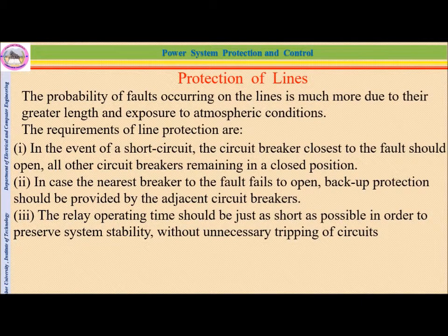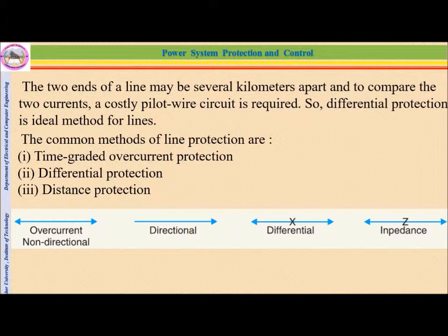The third one, the relay operating time should be as short as possible in order to preserve system stability, without unnecessary tripping of the circuit breaker. So they must be selective in a given zone.